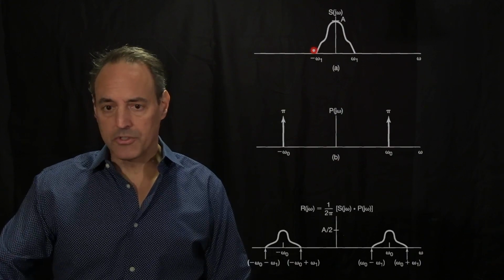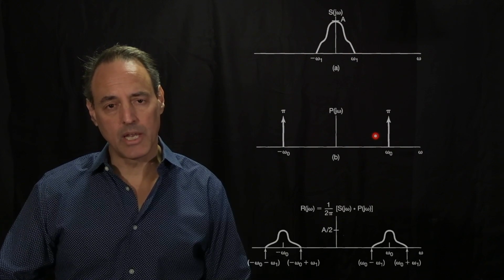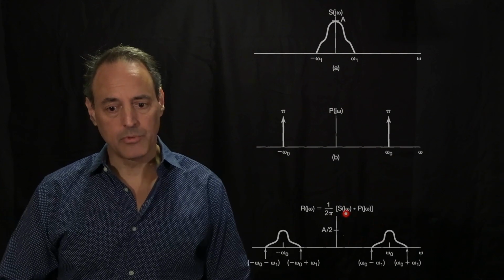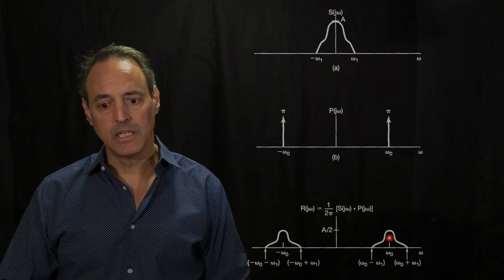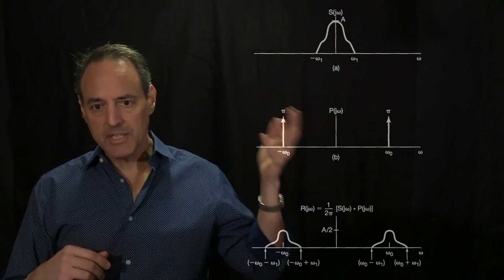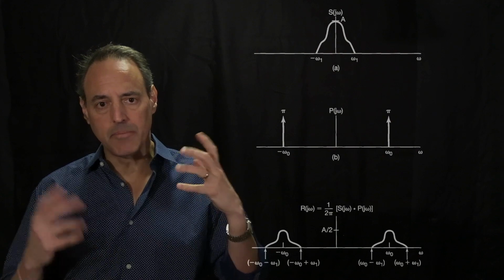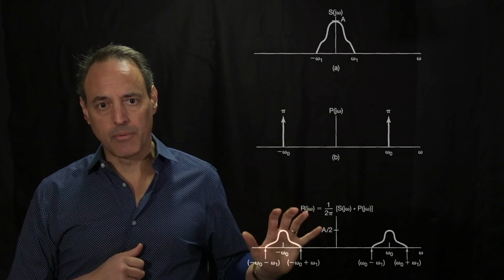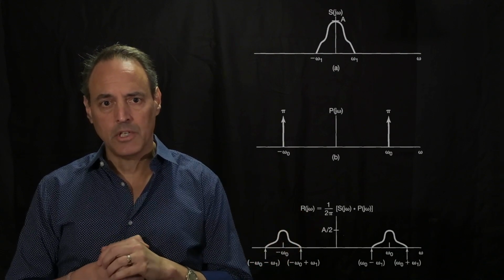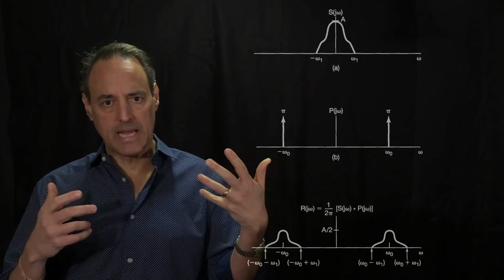So maybe my original signal x looks something like this in the Fourier domain. Here's what the cosine looked like. And when I convolve these two together, here's what the new signal looks like in the Fourier domain. Now I would inverse Fourier transform this to get my new signal z of t, where all I did was modulate my underlying signal x of t by a cosine, and now here's its Fourier representation once I modulate it. That was the impact that cosine had on this. So that's the idea: use one signal to modulate another to perform some kind of task.